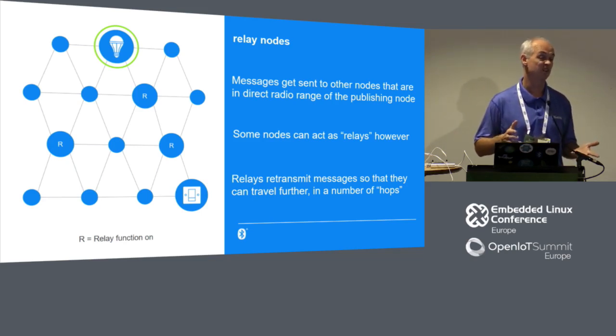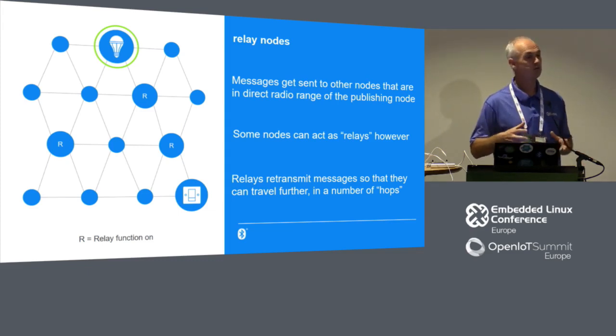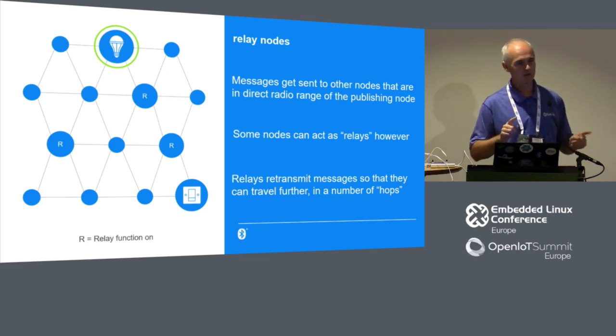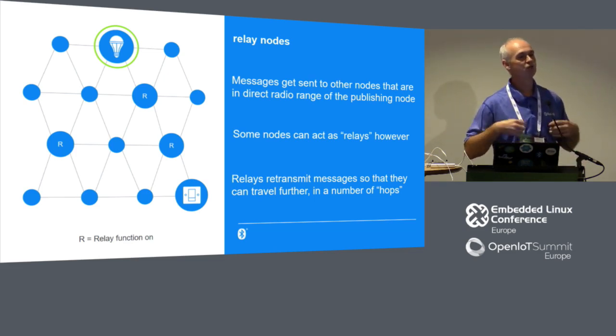So for small networks, there's almost no design work to do, no thinking. Something at home is just going to work. You don't need to give a lot of thought to it. For a big network, tens of thousands of devices like in a hotel, you do some design work. This is proper grown-up networking, and one of the things you'll do is figure out what devices need to be relays, where they need to be so that you get the range extension and multipath reliability that they give you. You don't want to go mad with this though, because every relay will introduce repetition of messages into the network and consume radio bandwidth. Rule of thumb is 5% of your nodes will be relays, give or take, but it's something you really do figure out for your network in your building. So there's some testing and optimization methodology you have to apply.